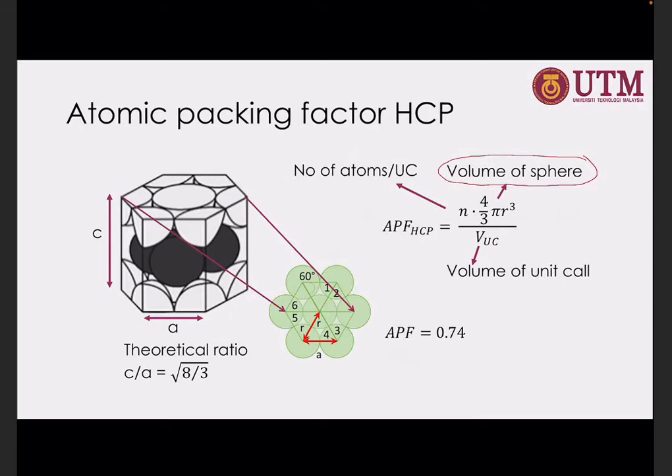That's the reason we measure the sphere to determine the atomic packing fraction, or factor. Then how packed it is in one cell, we call this cell a unit cell, we need to divide it by the space for this type of cell. So it is equivalent to 0.74.